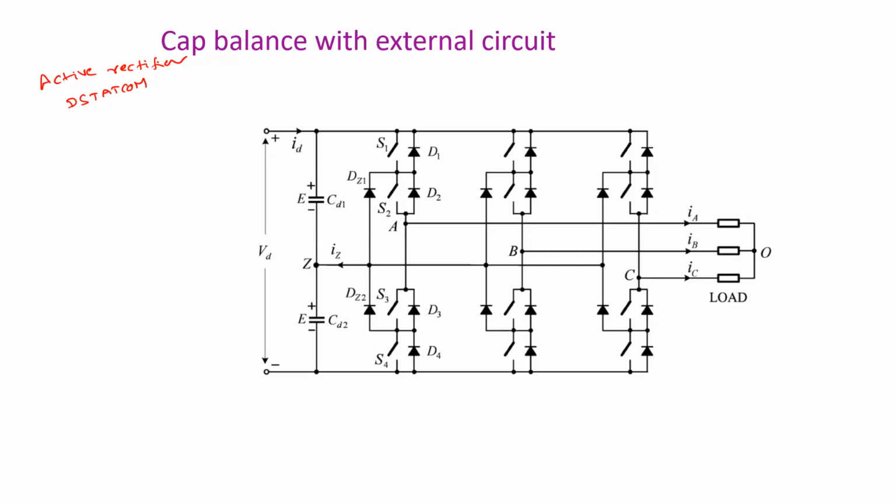If you are using it for a DCMLI, you must charge these capacitors with the appropriate voltages, and we have to make sure that these two capacitor voltages are balanced. This is a very difficult task when you are implementing it.